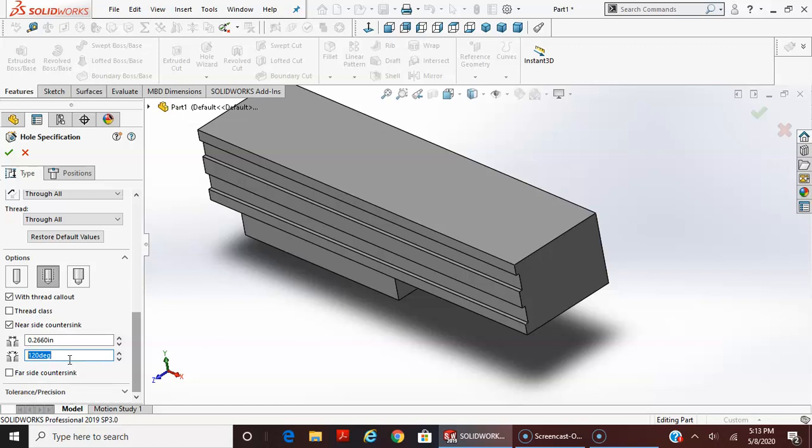So it engages the cutting lips of the drill tip quickly and evenly. And if you use a 120 degree spot drill, you're going to get a much more accurate location. Now on softer materials like aluminum, a lot of machinists will use just a 90 degree spot drill, and they can actually even establish the countersink, which is larger than the major diameter of the threads.